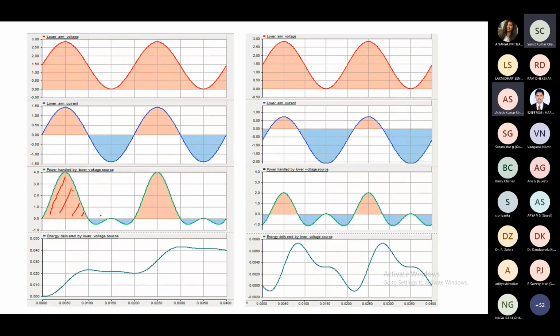Thank you. Yes. And on the other side, on the other cycle, this is the area when the charging is happening, and this charging area is really smaller compared to this discharging area. So this is the amount of instantaneous power handled. This area is the energy: the integration of the instantaneous power gives the final amount of energy handled. This is shown over 2 cycles. Assuming 50 Hertz, multiply it by 25, so you will be able to find out the power in watts.